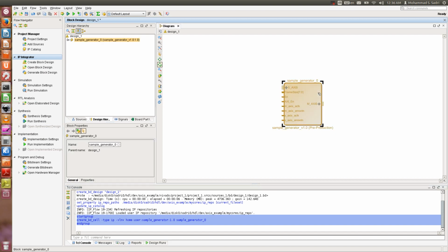This is the block, and what I want to do, usually it happens that in your design, the A to D, or the logic which is operating outside your ZYNQ device or outside your FPGA generally, is running at a different clock frequency than your internal circuit inside the FPGA.